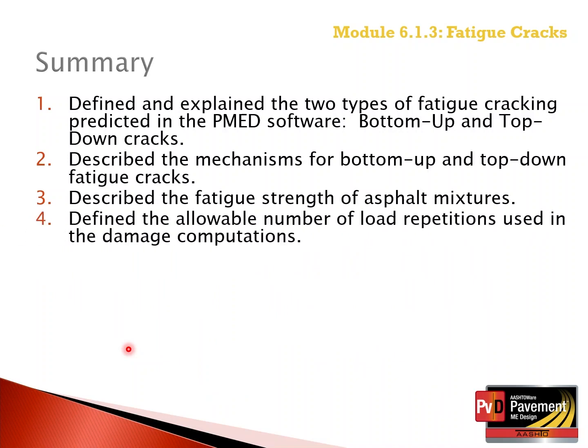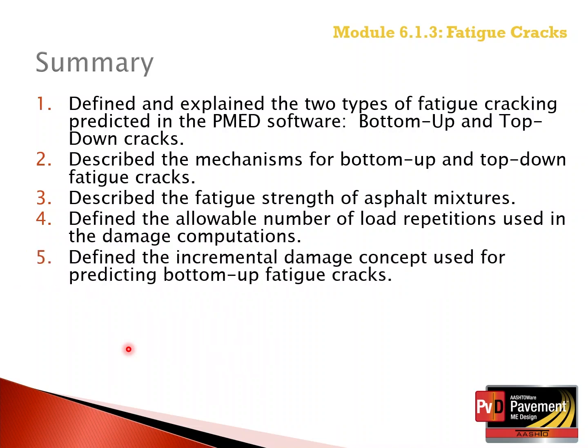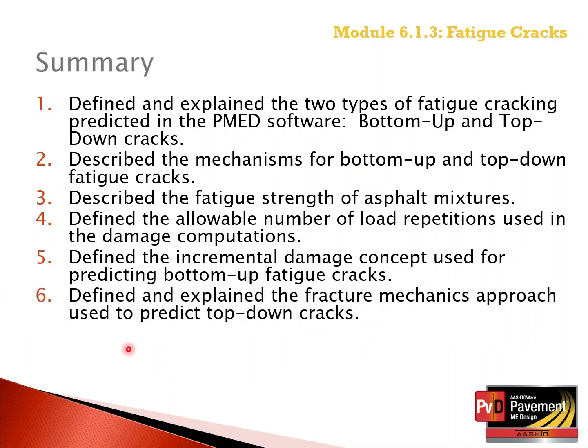We defined the allowable number of load applications used in the fatigue damage computations. We defined the incremental damage concept used for predicting bottom-up fatigue cracks, and we defined and explained the fracture mechanics approach used to predict top-down fatigue cracks.